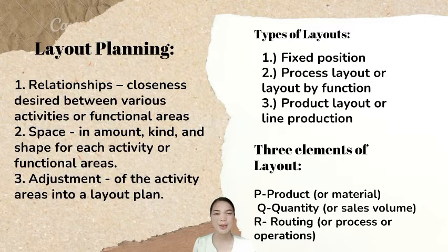As for process or function layout, it is generally most economical when the process is relatively specialized, the products are diversified or valuable, and the quantities of each item are relatively few.